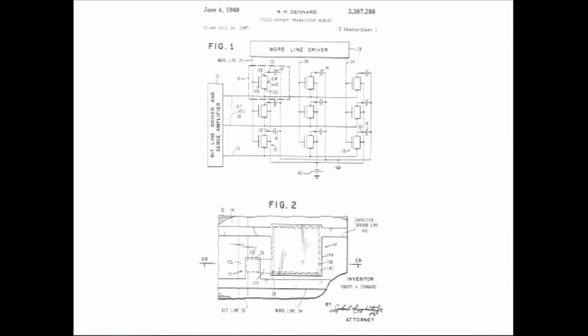So I went back to work with a few others to design and prove a prototype of a 512-bit chip using the 6-transistor cell. Later on, this 6-transistor cell came to be called static RAM, after a dynamic RAM was named. In time, we completed the research and development work on the MOS transistor process, wrote up a design manual, and transferred it to manufacturing.